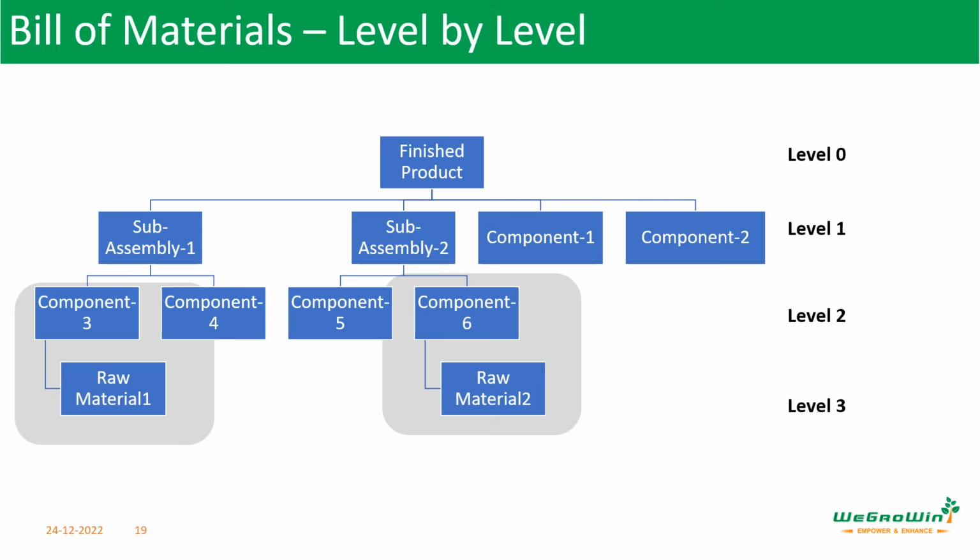So here we are seeing the bill of material step by step, right? Producing the first level, what are the components required, and then the next level, for each one, what are the things we require. Like this we go level by level. So this will give you a hierarchical structure of the bill of material, and it will be required when we do some analysis of how the BOM components are there, how the critical points are there, how critical work centers, which material is critical to see them. This kind of level by level approach will be useful.